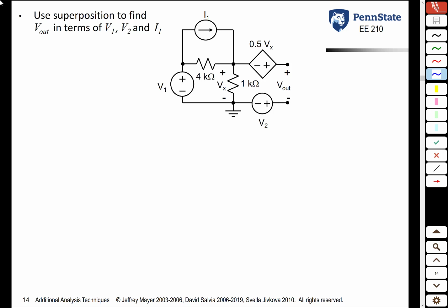In our last class, we introduced two new circuit analysis techniques, linearity and superposition. In superposition, the idea is to take a more complicated circuit and break it down into multiple simpler circuits by activating only one independent source at a time. In today's lecture, we will do two more examples with superposition before switching over to the main topic in this packet of notes, Thevenin's Theorem.